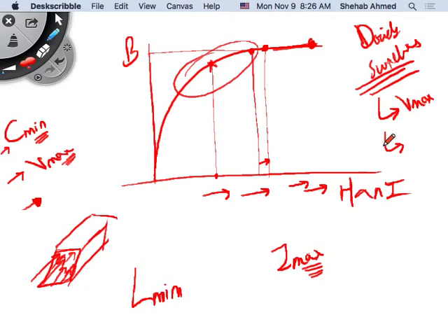No, max switching frequency is a byproduct as well. It's something that you filter on later. Remember, we chose two parameters, and then we were left with a set of switches. The set of switches had different rise times and fall times, different RDS-ons or turn-on resistances. They had different other characteristics.